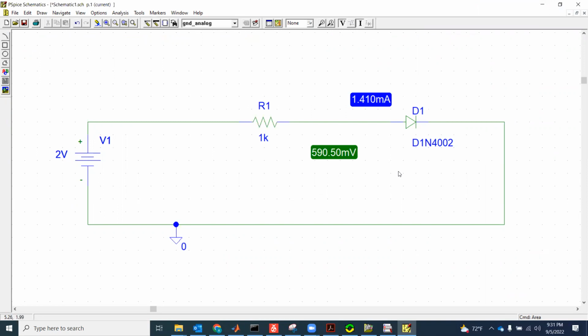And for sure, guys, as you know, the diode characteristics should be plotted in forward bias and reverse bias. So we need to apply positive volt and negative volt and figure out what the voltage and current across this diode would be.